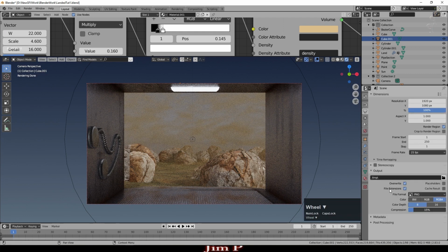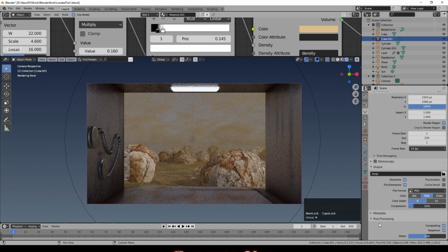So next, let's set how this scene works. We don't need to render alpha, so we can turn that off. We can render at 16-bit color depth. Generally, it's not necessary. And the defaults for post-processing with dither are generally fine. You might need to increase that if you have a very gradual graded, for example, sky, and you were getting banding. Increasing this dithering will often help with that.